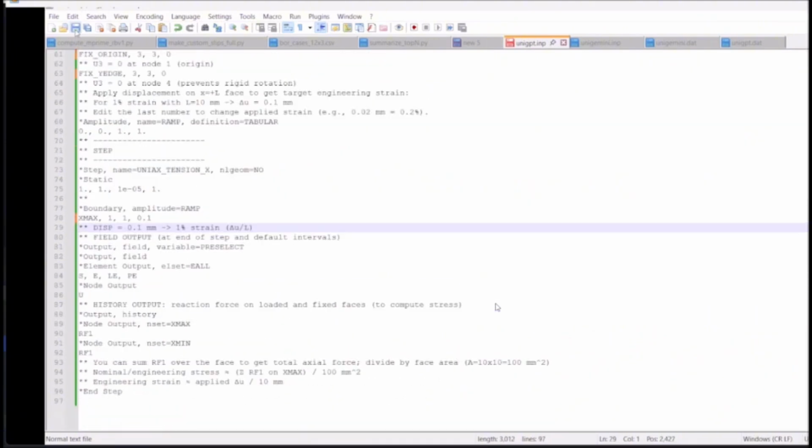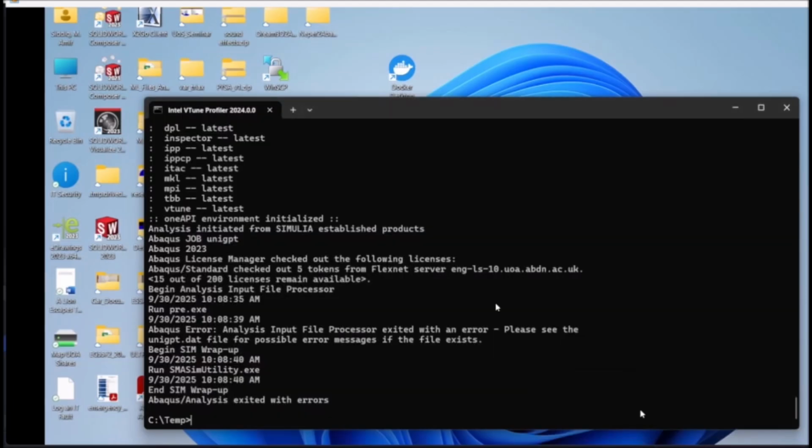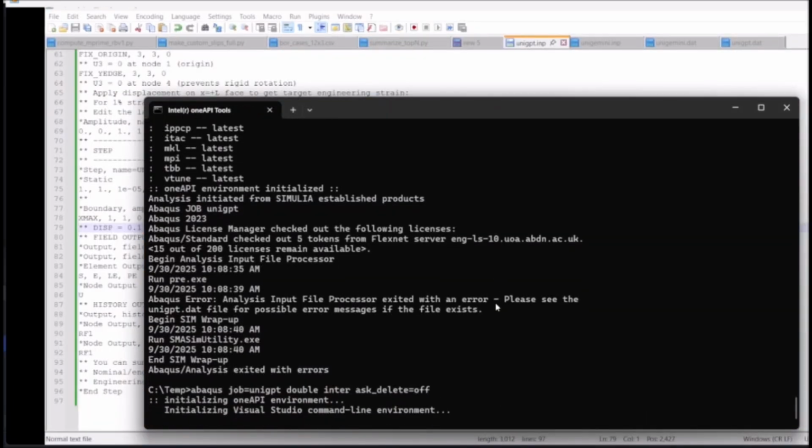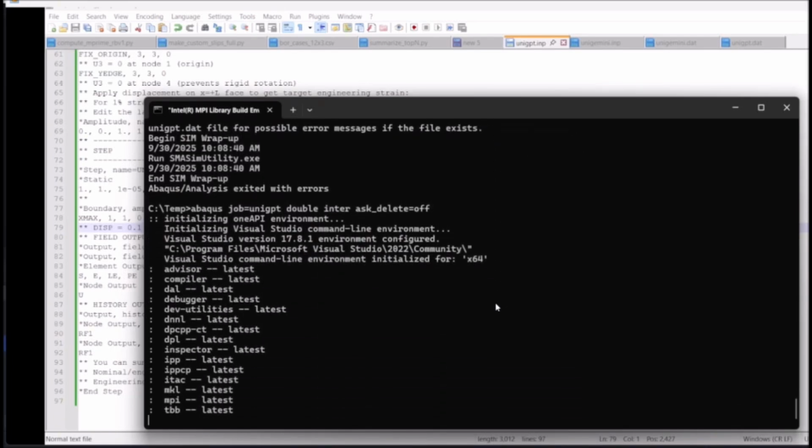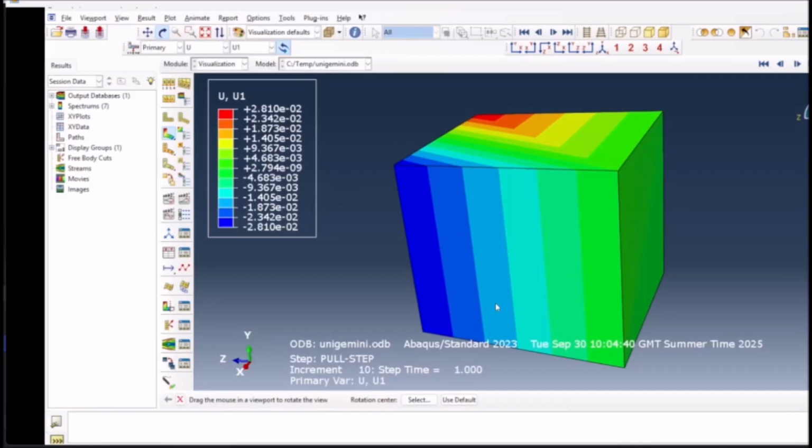What I have found is if you copy the whole code and the error message in ChatGPT, it can find the error and it can remove those errors for you and give you a new input file as well. So you can do that as well. In this case, I'm doing it manually because I know what the problem is, but you can try that, and in a few iterations you will see your model work. So now the job finished, everything worked fine.